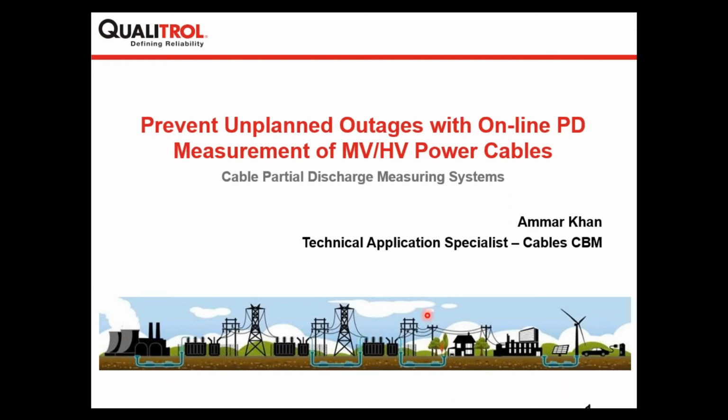So you can integrate the same RAUs at the cable terminations and connect them to the server, but you will have a different software platform for online partial discharge measurement in the cables.